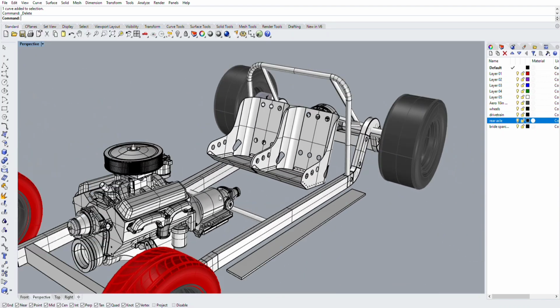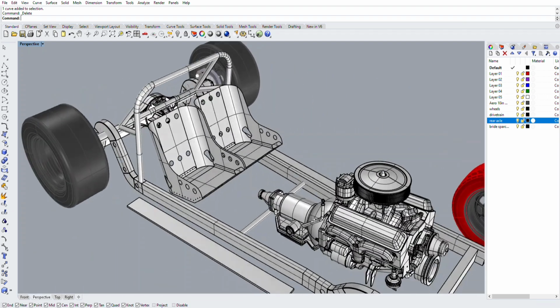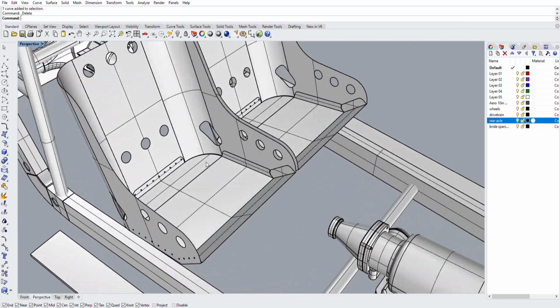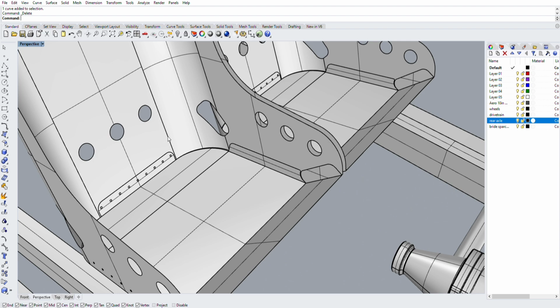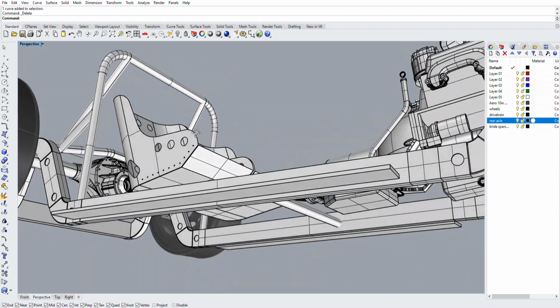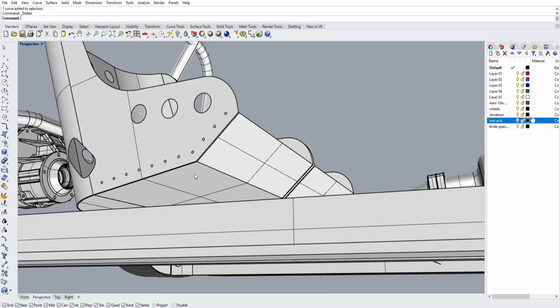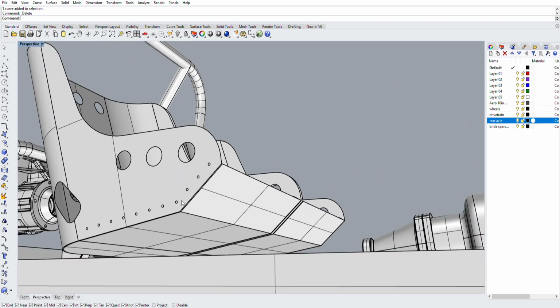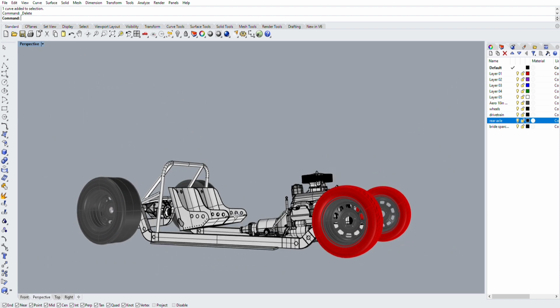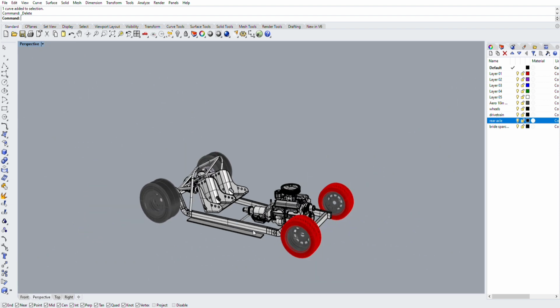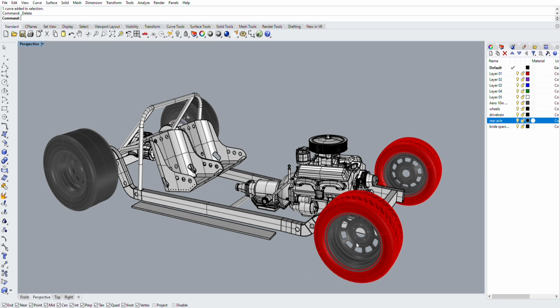I love doing this stuff because it gives me some visual cues. I can look at the space. I know that if I move these out 3 inches, I can get my drive shaft through. My tunnel will be tight, but I know it'll fit. On the underside here, I'm planning some ribbed braces, kind of where the cursor's going there. And I may actually mount them with tabs kind of from the side, like modern racing buckets use. I haven't quite determined that, but that would be a really easy addition to the file.